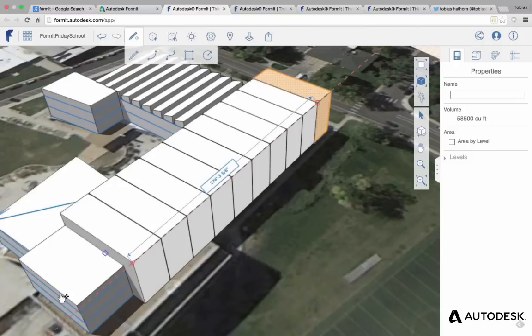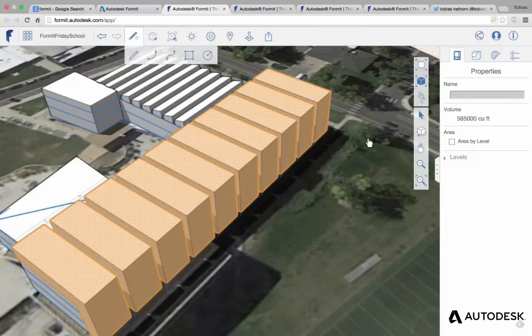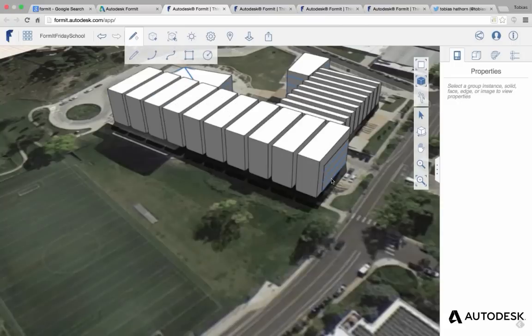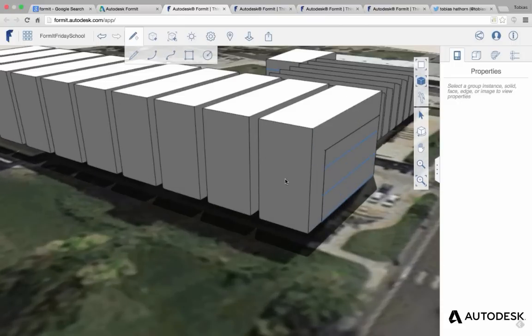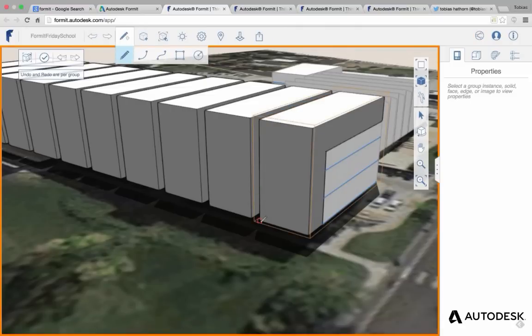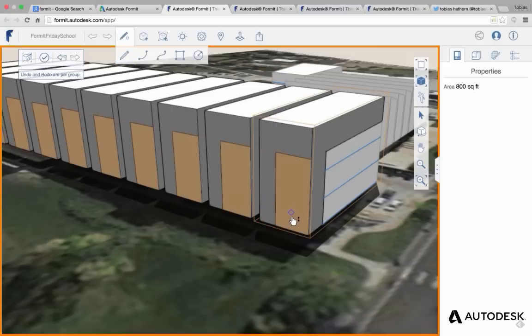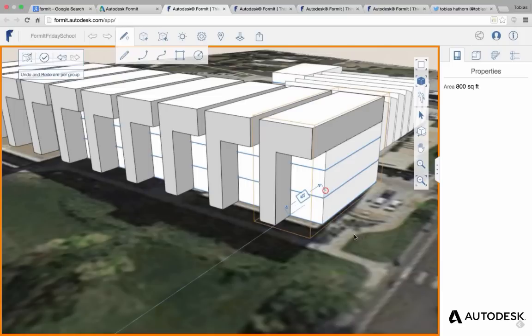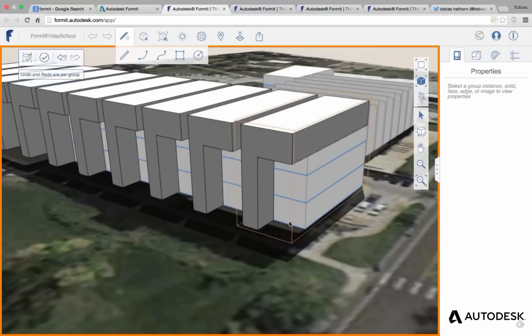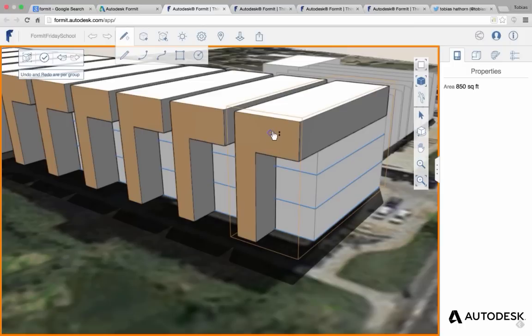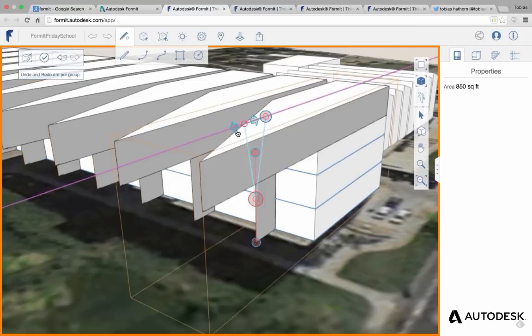And so this is pretty cool that you can start to carve away the geometry and edit these all at once. So draw this guy out 10 foot, draw this guy up 40 feet, come across this way another 20 feet, and you can select that face and push it in so it takes it all out. You can select a face, right click, and use a tilt face command so you can actually drag out your face a specific distance if you wanted to.